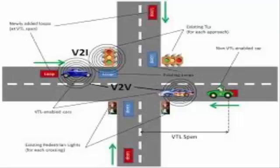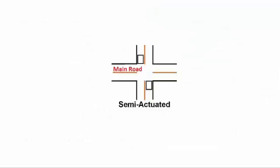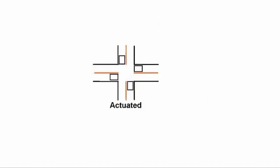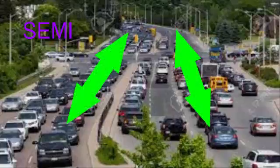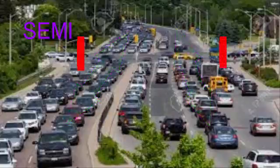There are two types of controllers that are used for different traffic flow settings. One is semi-actuated and the second is full actuated. Semi-actuated controllers are used for major roads that have a constant flow of traffic throughout the day. Their main function is to prioritize traffic on bigger roads by controlling the light intervals of smaller roads. They receive information from detectors installed on the smaller roads so that they are able to give the right-of-way to vehicles on the smaller streets when necessary, while keeping minimal disruption to the flow on the larger street.